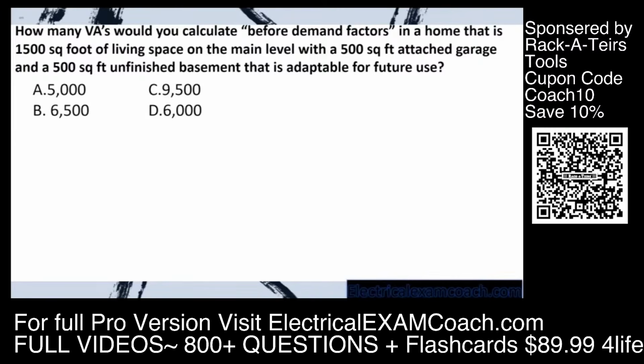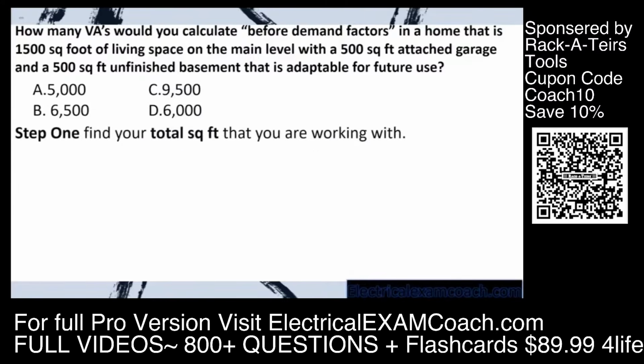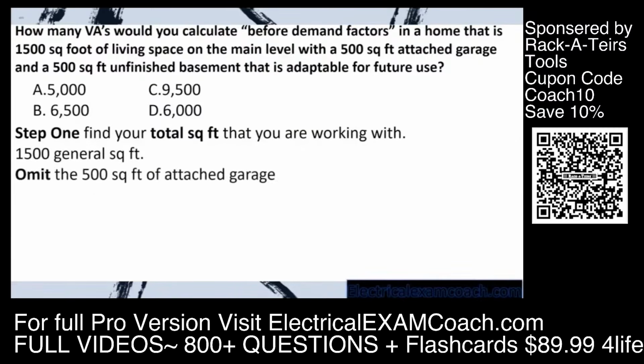How many VAs would you calculate before demand factors in a home that is 1,500 square foot of living space on the main level with a 500 square foot attached garage and a 500 square foot unfinished basement that is adaptable for future use? Step 1 is find what our total square feet that we're working with. So we have our 1500 general. We will count it. Then we're going to omit the 500 square foot of attached garage.